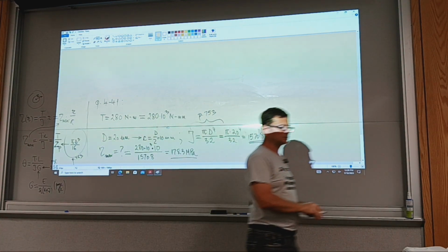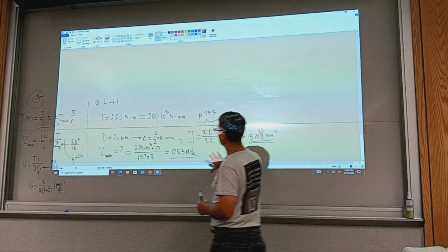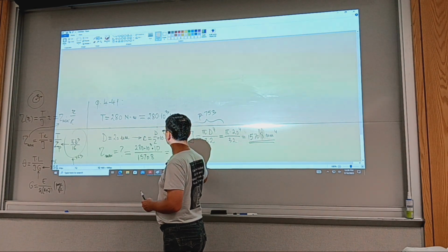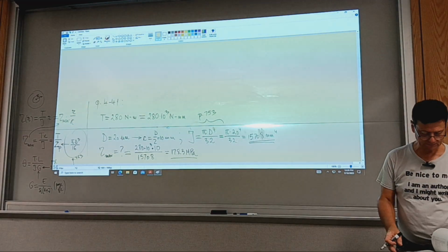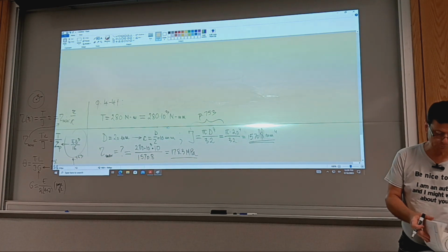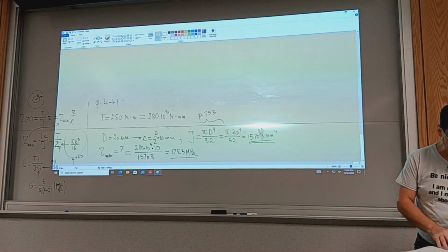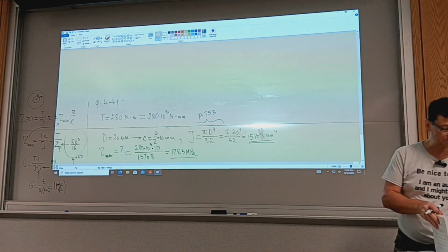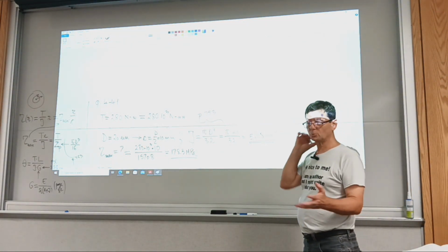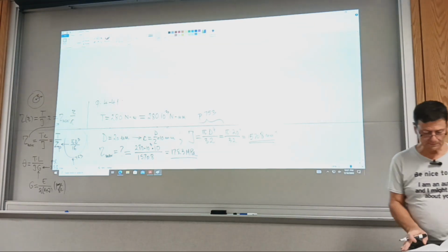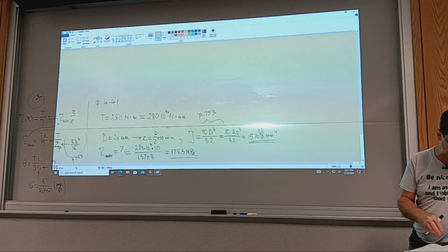Okay, so we have a stress. We don't know the properties of the material that the shaft is made of, but if it was given, we could add to this. So let's assume, making up quickly a material, let's select the material that is proper for this application. Let's assume it's a steady torque, for which the design factor would be, and to get that, it's page 709, which is a summary of design factors.